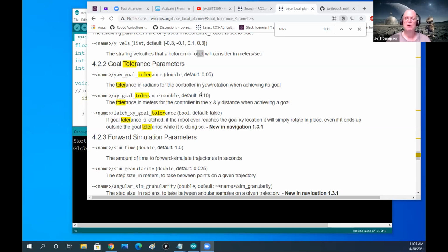And then set the goal tolerance, the angle tolerance within that, probably to like 6.28, which is a full circle. Then anything when you get there, it'll keep both of those happy. So that might fix your problem. And then as Juan says, go into the actual TEB planner and say don't allow it to back up, and that might help out too.